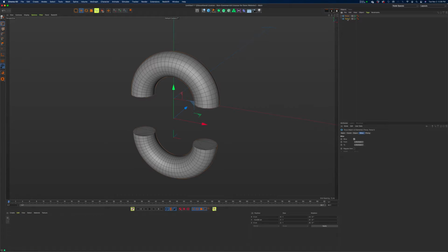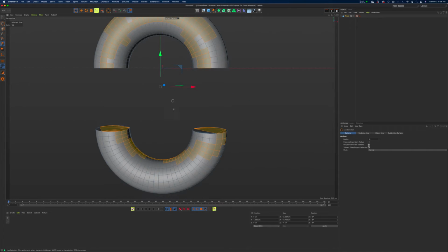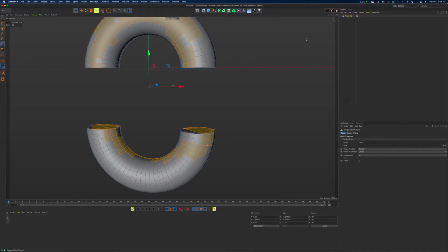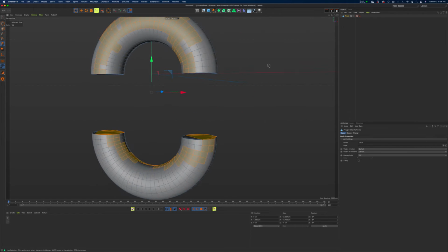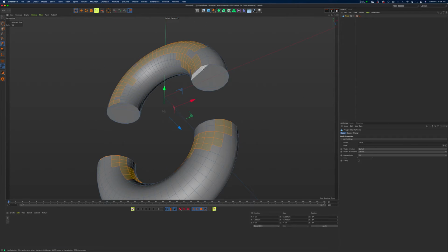If I select both of these two right here, I'm just in object mode. If I right click and I say connect objects and delete, even though I hadn't done the make edit command, because I combined them, it turned them into raw polygon objects and then connected the two of them. So if I go into polygon mode and I select, even though these are two islands of polygons, they're the same object. That's in there, okay? So that's the first part of this. This is working fine. There's another issue that we've created here, but let's first deal with the connecting.